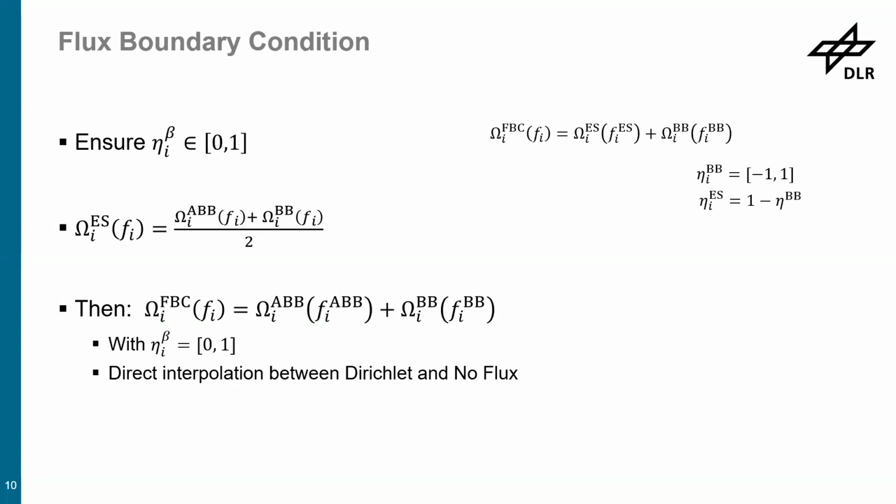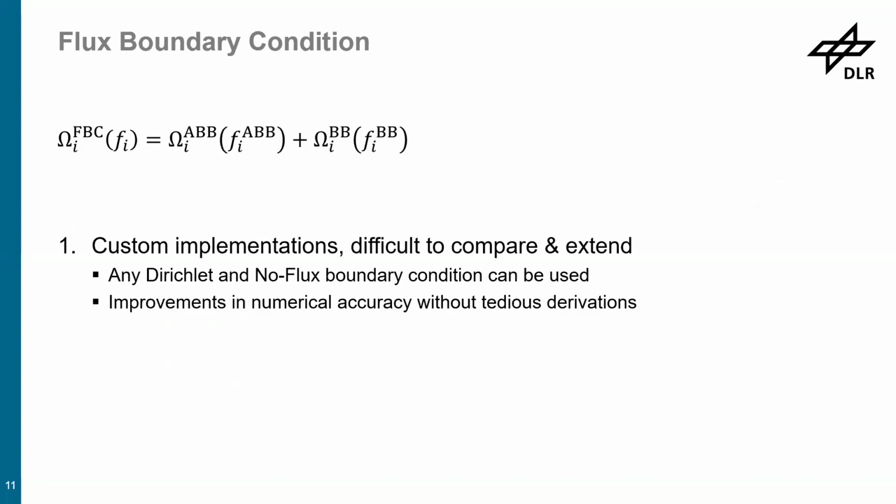So that is a very charming way of looking at it, because we can then use this information to extrapolate it to other scenarios. For example, we can implement wall velocities or any kind of other velocities into the equations directly without any additional derivations. And we can replace the collision operators with physically equivalent ones. So for example, instead of bounce back, we can take the non-equilibrium bounce back if we want to.